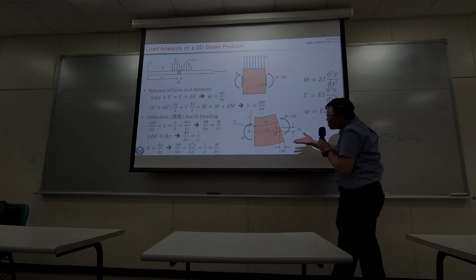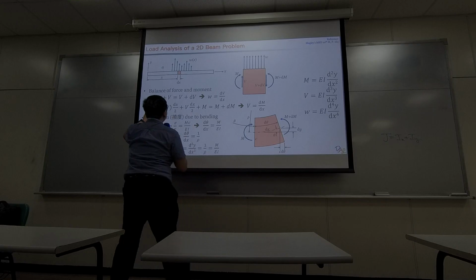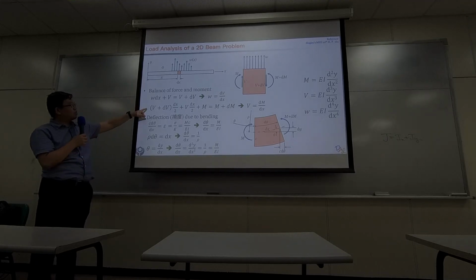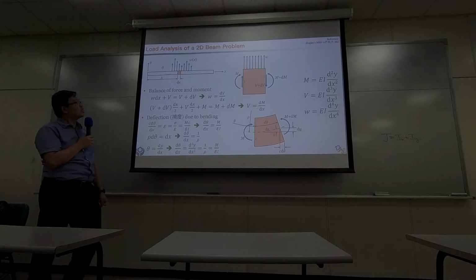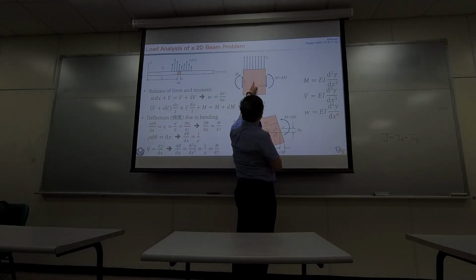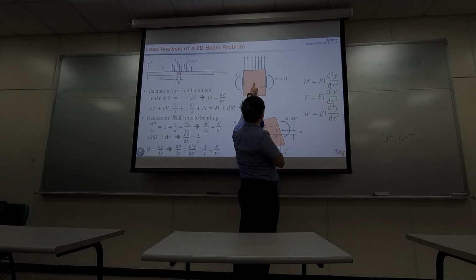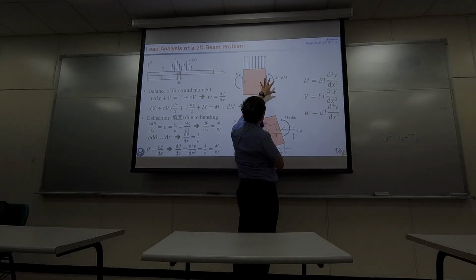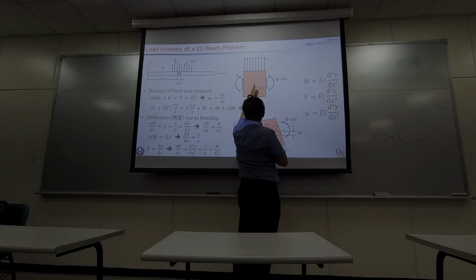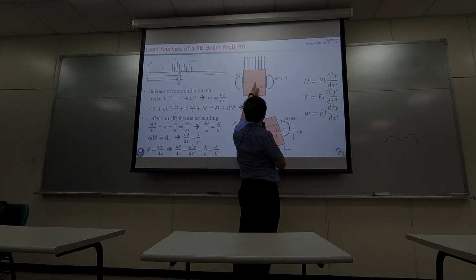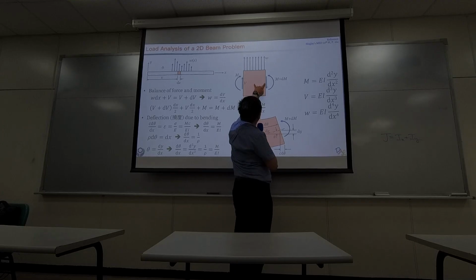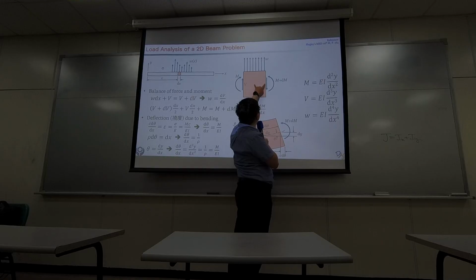So the relationship between W and the increment of the shearing force can be derived right here. Okay? Secondly, we will use balance of moment. Everything that rotates will be expressed right here. You can treat the center as a supporting point, and you need to figure out what will be generating moment about the center point. Right now, V plus dV is going to generate a clockwise moment with a half dx radius right here.